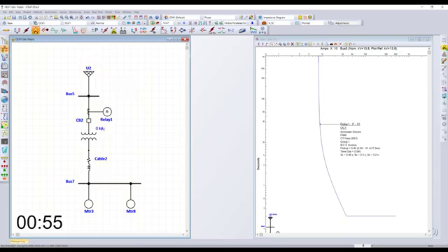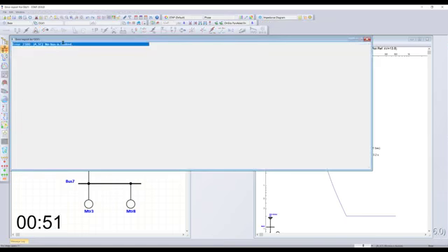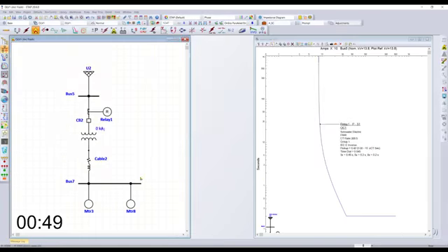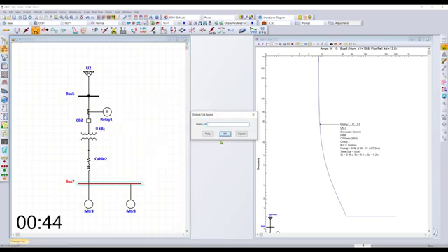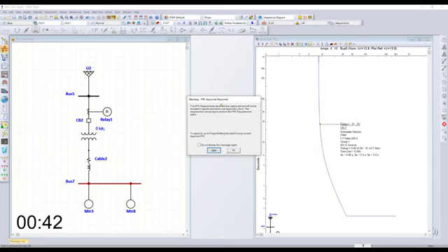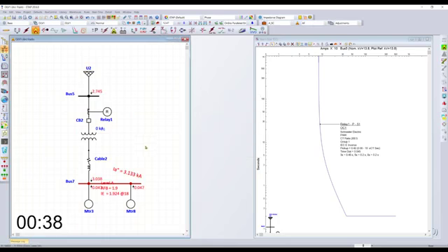And with that, we can switch over to arc flash and run our arc flash computation. We need to select a bus where we want to fault, so we can right click and fault, and run our arc flash study. The program gives a warning that the PPE requirements have not been approved, so it's essentially doing a safety check. And then based on the current short circuit results and the relay setting in the network, we can see what the arcing current is, as well as the arc flash energy.